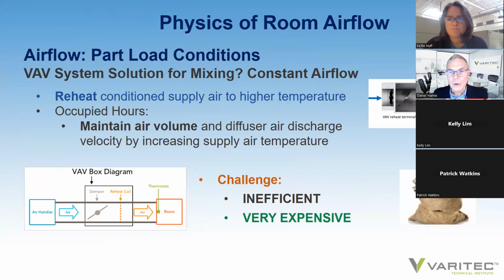In healthcare, I use the application because per ASHRAE Standard 170, your air change rates are fixed per space, regardless of the load. So you have a constant flow of air in the space. And in order to condition the space temperature, out of a VAV box, you have a reheat coil, and the temperature of the reheat coil increases or decreases to maintain the temperature while the air changes in the space remain the same per ASHRAE standard requirements.